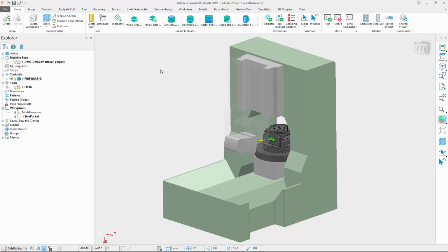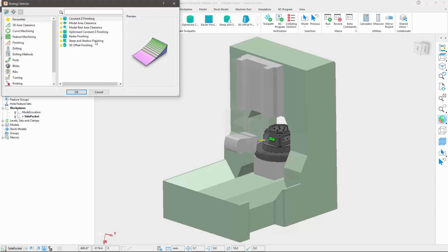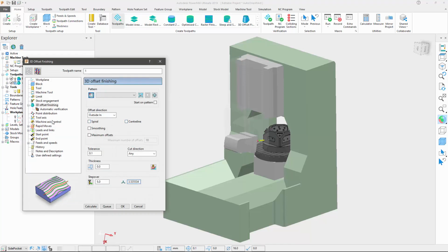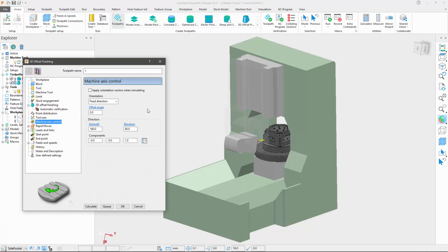Any 5-axis machine, when not in gimbal lock position, will only have two mathematically possible solutions to reach a given point with a given tool vector. Historically, it has been difficult for Powermill users to know what a good choice for the orientation vectors was. Hence, many programmers have them set by the startup macro to a fixed direction, with the azimuth angle often set to 0, 90, 180 or 270 degrees.